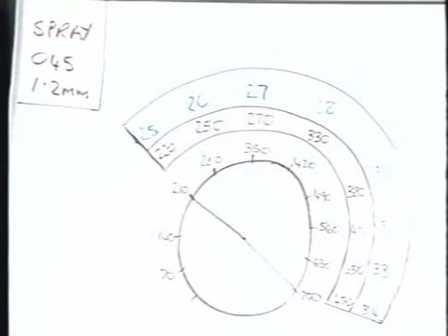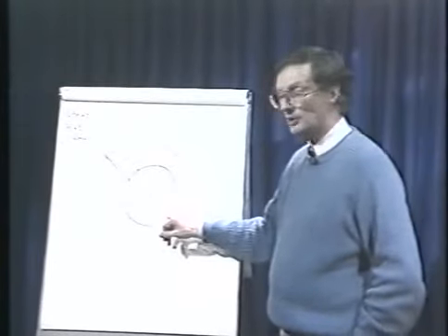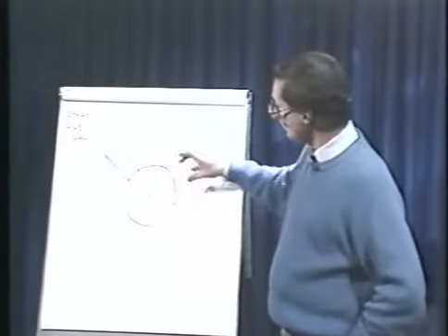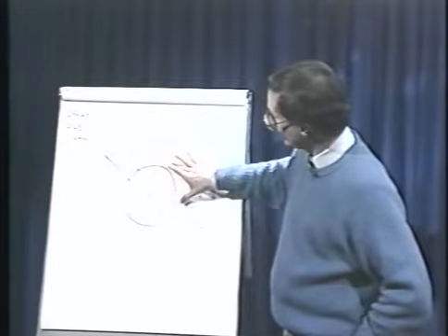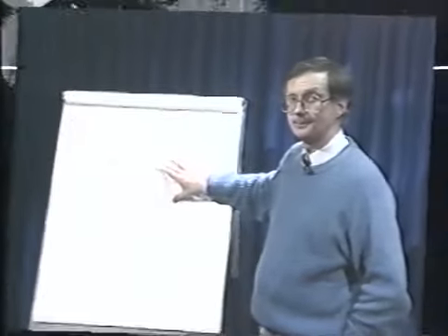If you need to go to 3/8 steel, then you would traditionally be again at the 3 o'clock position. Once you open up wide open with an 045, you start to get a turbulence effect on the weld puddle down at the higher end. Most of the welding with 045 is done between the 1 and 4 o'clock position on high deposition work.